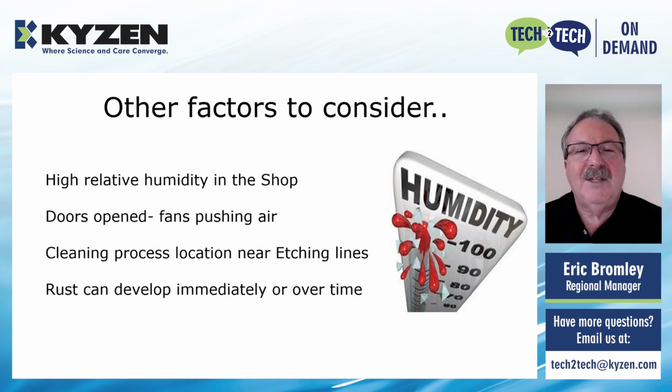If the cleaning process happens to be located near an etching or a passivation line, then the boiling tanks, that moisture can transfer over, and as it cools, it'll settle back down onto whatever it wants to, and it can be your parts, and that'll cause rusting. So if you have a mysterious rusting in a certain area and it happens to be one spot of the building versus the other, that's the likely cause. This moisture is redepositing from another operation.